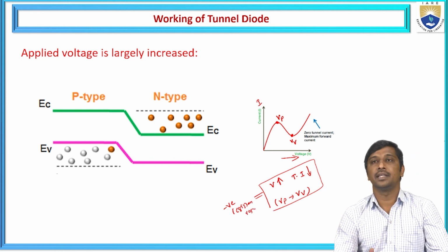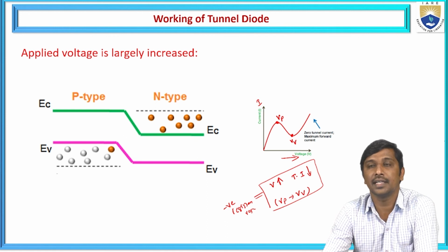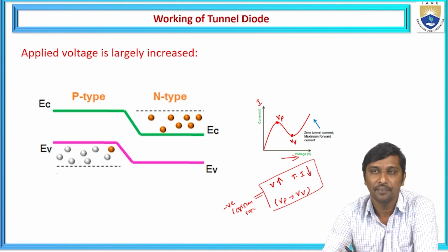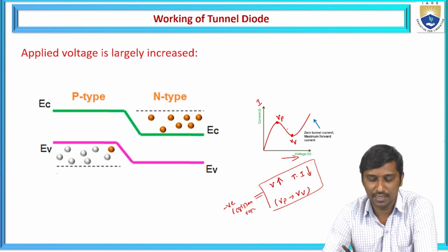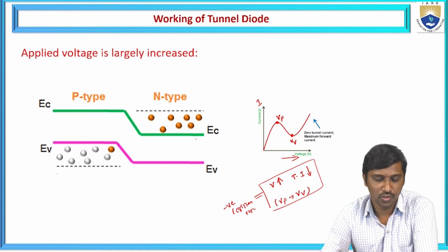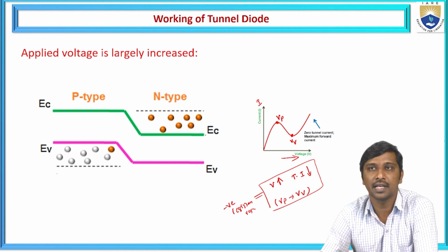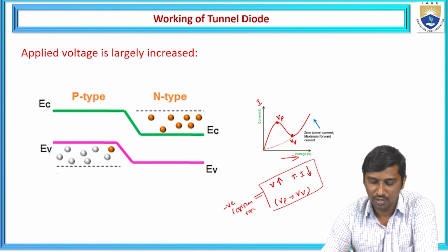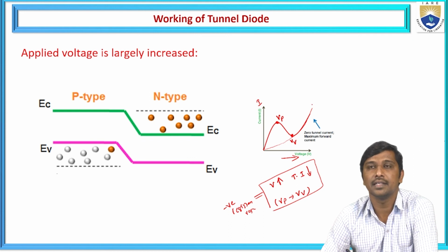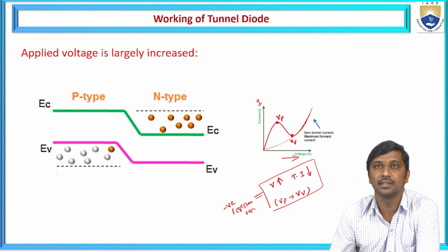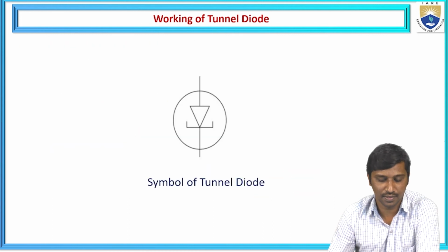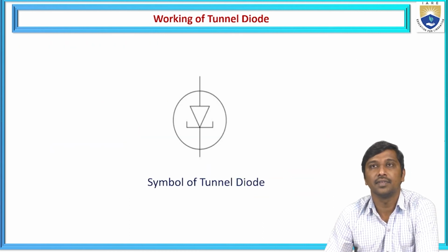That is the reason we said initially that the tunnel diode or Esaki diode is a thin junction negative resistance device. So from the VP region to the VV region, the tunnel diode satisfies the negative resistance characteristic. If it goes on increasing again, breakdown occurs, hence there is no control over the movement of the charge carriers, and the conduction rate increases again. So that is the VI characteristics of the tunnel diode.